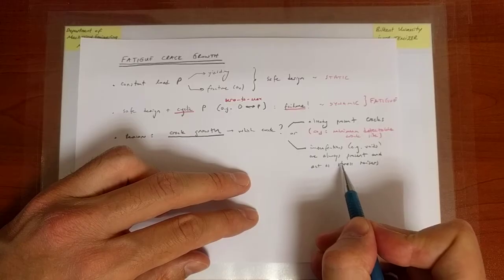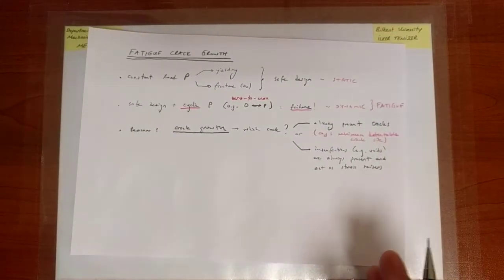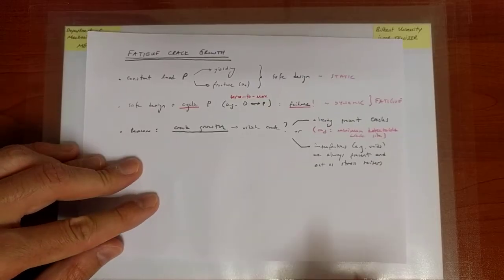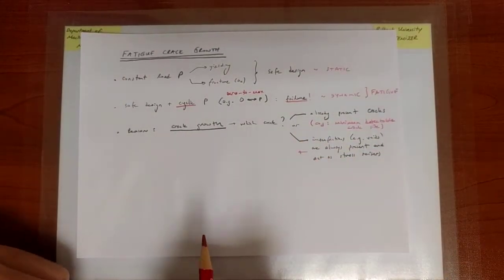So the stress in the vicinity of the void is actually larger than the stresses slightly away from the void, and eventually these stresses could be sufficient to cause local failure of the material, and this local failure could accumulate to an extent that eventually a crack starts to form in the vicinity of the imperfection.